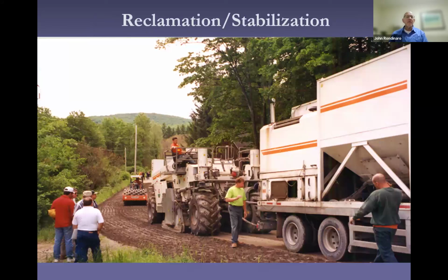And then finally, when that road is too far gone and you really don't have a thick enough asphalt section to cold in place, reclamation stabilization, FDR, is a great choice. The one thing I want to point out here is, if you'll notice on the left-hand side of that slide, that's a sheep's foot roller. When you see a sheep's foot roller, that's telling you you're doing earthwork now. You're not creating an asphalt base or binder anymore. You're now creating a new granular foundation for your roadway section.